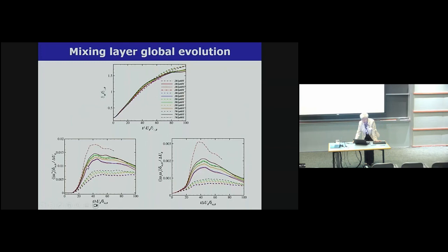And you can see that for the Reynolds number, R1 is in broken line, R2 is in solid lines, and R3 here is in dashed dot, okay? So you can see that vorticity is very much affected by the composition, okay? Here is a lower Reynolds number, R1, R2, and this is R3 for the 2 species. So they're bunching, so the Reynolds number is very important, but it's not the same positive span-wise vorticity, and they're bunching according to the Reynolds number, but there's a divergence there according to the number of species.